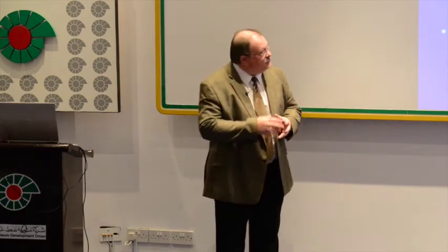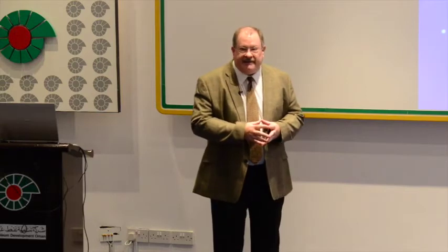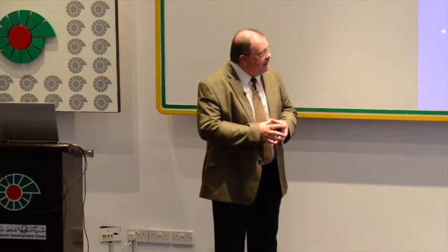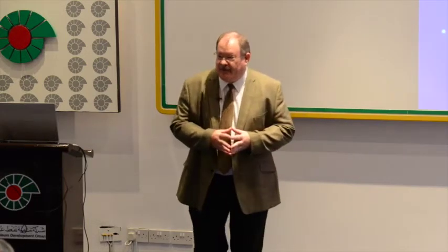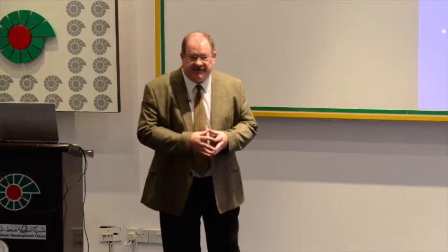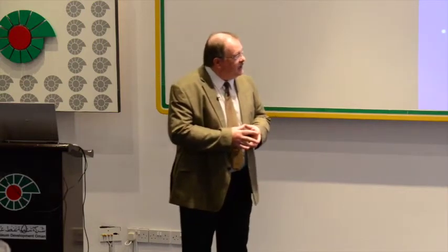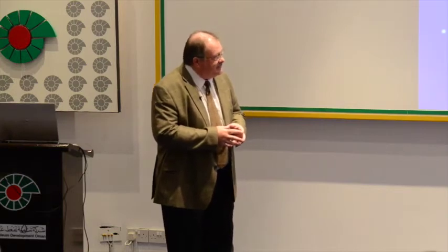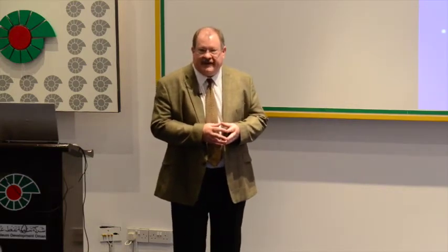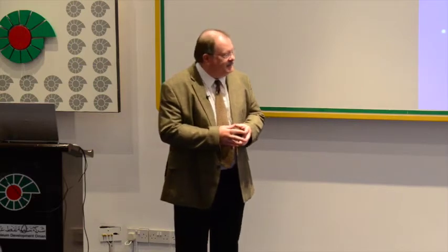In these very tight reservoirs, we've got to be focused on the initial rate and the decline, because we're going to have low recovery factors. We're not going to have a big tank of gas where we get a 70% recovery factor just because it's a depletion drive mechanism. The recovery factor is going to be low. In this situation, it's not the storage capacity but the flow capacity. What's the kh, the permeability thickness of the reservoir?